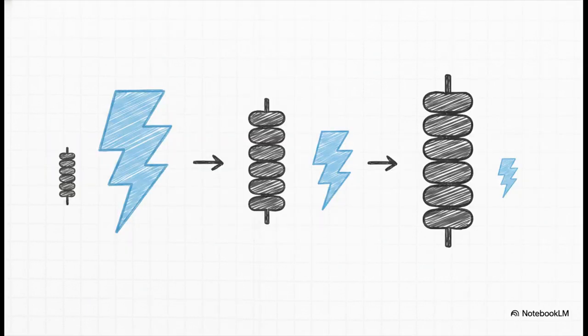So here is the absolute crucial mathematical progression you need to memorize as a planning engineer. Sub-transient reactance is less than transient reactance, which is less than synchronous reactance. It's that simple. Because of Ohm's law, as time passes after a fault, the generator's internal impedance is increasing, which means the AC fault current is decreasing from that massive initial spike down to a lower, steady value.